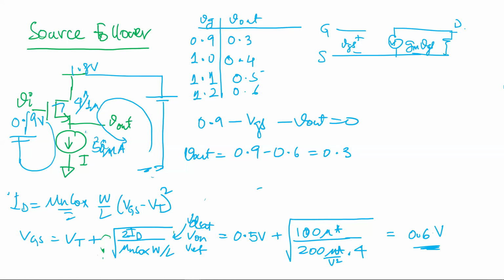So you take the gate, source, drain, substitute with this model, make the independent sources 0, and for this circuit, calculate V out over V in, the small signal V out over V in. Obviously it will be in terms of gm and RDS.